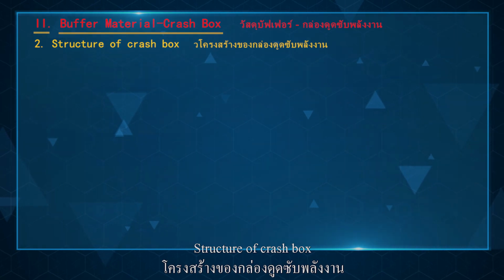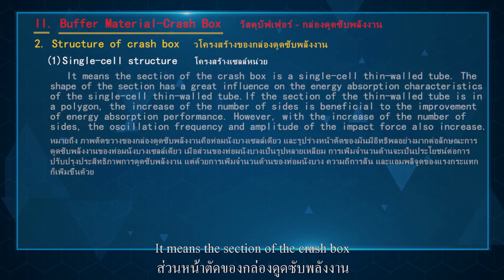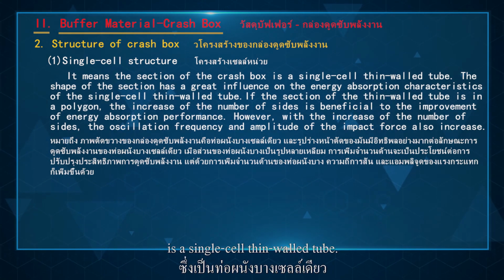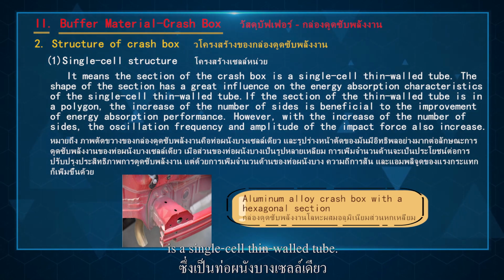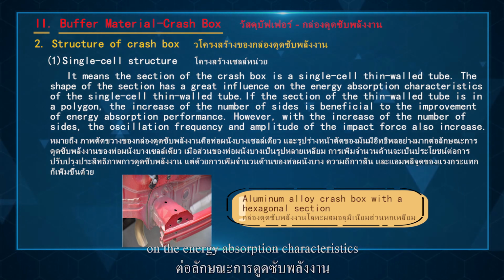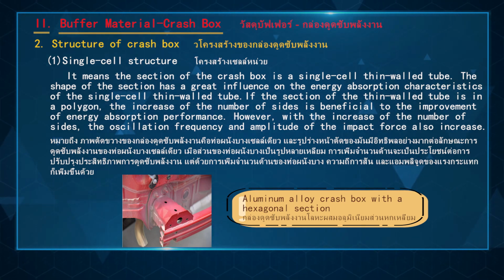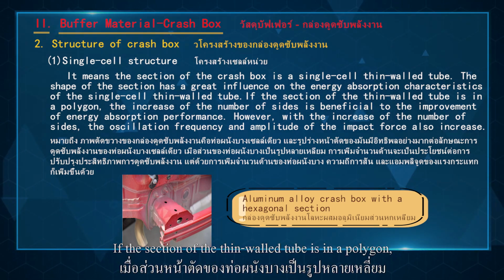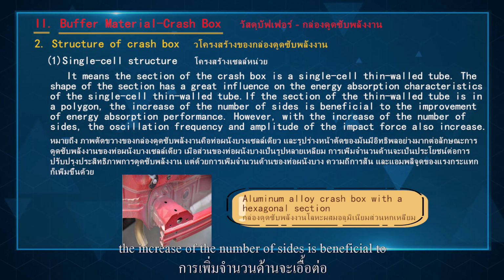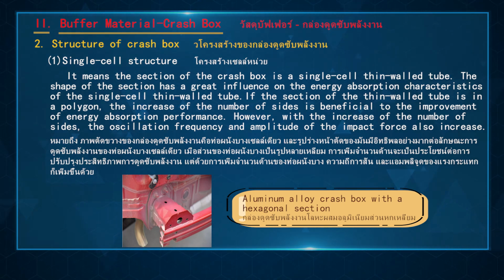Structure of crash box. 1. Single cell structure. It means the section of the crash box is a single cell thin wall tube. The shape of the section has a great influence on the energy absorption characteristics of the single cell thin wall tube. If the section of the thin wall tube is in a polygon, the increase of the number of sides is beneficial to the improvement of energy absorption performance.